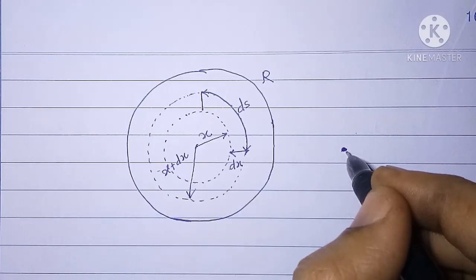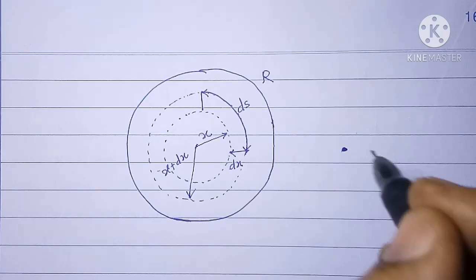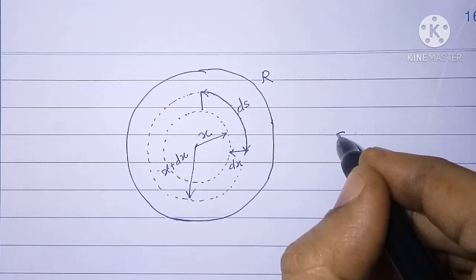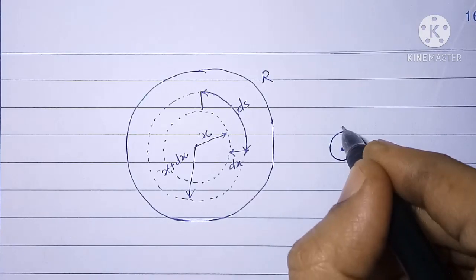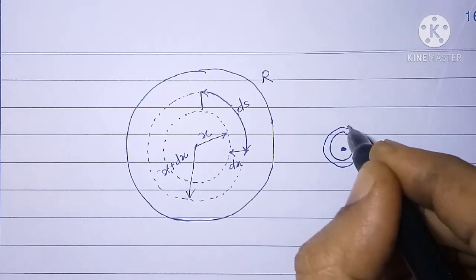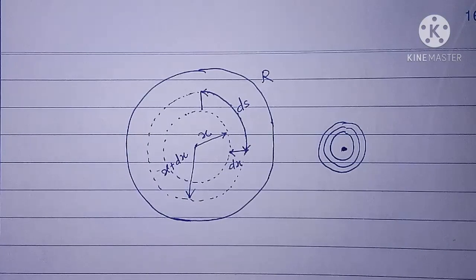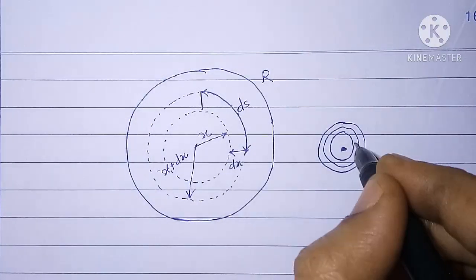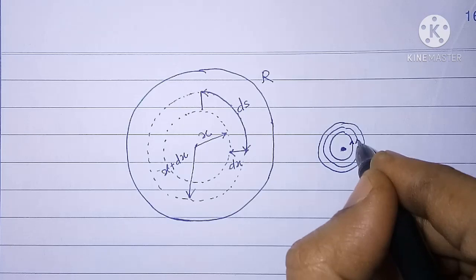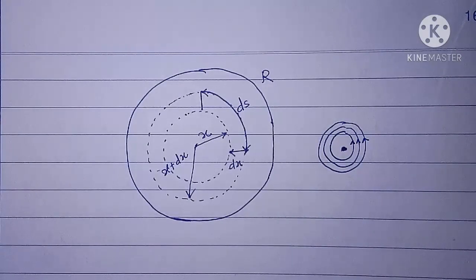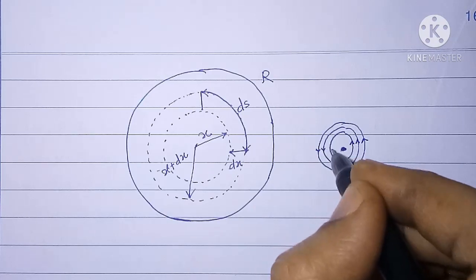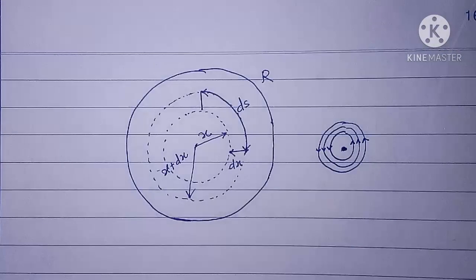We know that if it is direction of current in the conductor, that is current is flowing outward, then the flux will be appearing like circular rings around it, and the direction of this flux can be found by using right hand thumb rule. Accordingly now the flux appears to be anti-clockwise in direction.